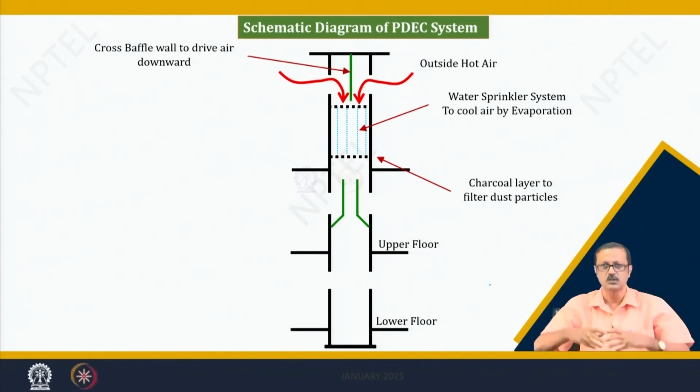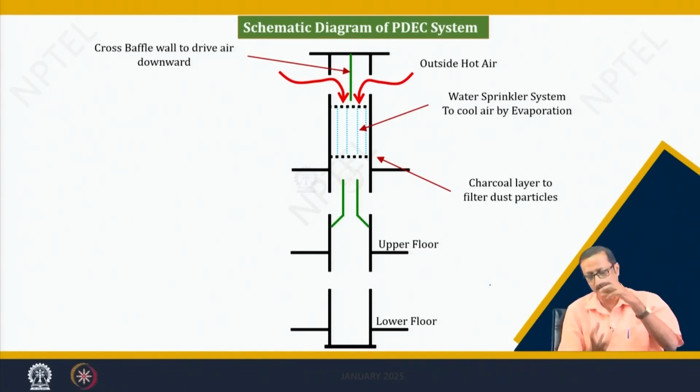So, water will sprinkle from top to bottom, or probably from bottom to top and bottom, something like that, and that will be arranged such that whenever the air flows down, it should pass through this wet water wall or surfaces. There may be some kind of honeycomb surface, which is always kept wet by a water sprinkler, and air passes through that honeycomb surface, moving through those holes and pores as it goes down, and maybe there is another fan below which again drives the downdraft a bit.